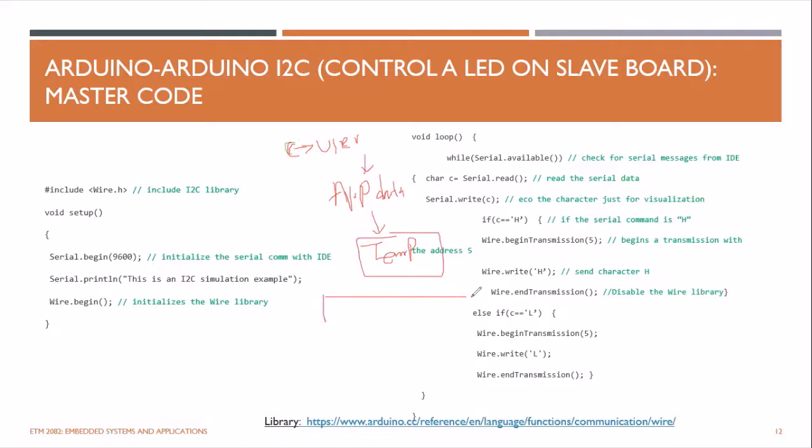There will be something like an Arduino folder. If you compile your code at, let's say, 10:45 a.m., you can just see there's a folder at that time. If you go inside, there will be a hex file with the name that you saved your Arduino sketch. So copy that hex file and import it to your